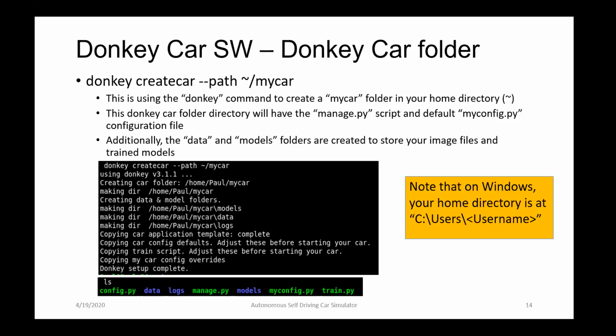But yeah, and Paul, really quick, just a follow up on that: if you already have a working model and you just want to collect a little bit more data, you don't have to retrain on your entire directory of data. You can then do something that's called a transfer model. So you're going to train, give a new model number, and tell it the tub. So now the inference is going to be based on something that's already worked. You're going to add some more data for it and create a new model. So you don't have to do a training that will take you like an hour or so. You can just do something in 5 minutes.